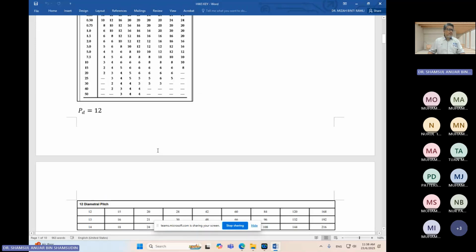But if you choose a simple gear train, everything in one plane, everything one gear next to another, if there are 10 gears touching each other like a train, in that case you do not have the liberty to choose different PD. Okay, because they are touching each other. Because the condition to connect the gears is that the PD must be the same, and also the pressure angle must be the same. If you choose 25, all gears must be 25. You cannot have one 25, one 20, one 14.5. So all must have the same pressure angle and the same PD.